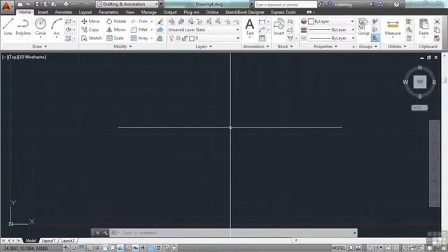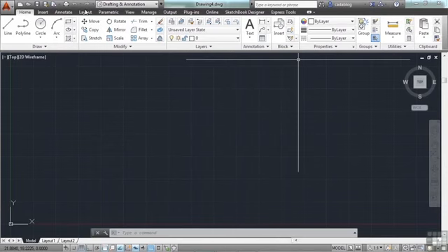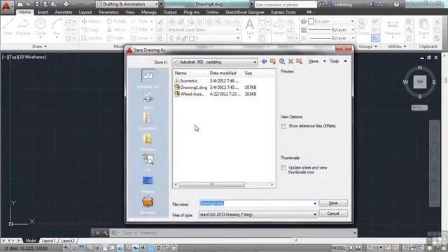I know that sounds kind of scary. Like, what do you mean you can't save your file? Well, if I go and click save or type in the word save, AutoCAD won't let me. It just says, hey, where do you want to save it and what do you want to call this file? It will use the default name that it gives it when you start it, or I can replace that. But I have to save it somewhere else. I'm not going to override my template file, and that's exactly what I want. Your template file needs to stay untouched, and not messed up.